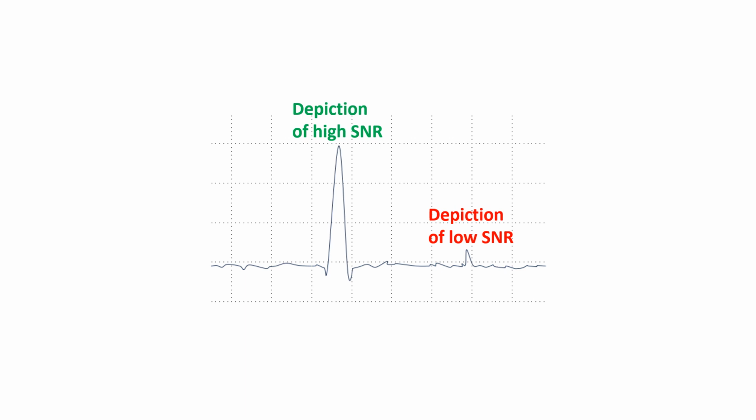A good communications receiver should have an SNR of 5 to 10 dB in bands below 30 MHz. A high SNR means that the signal is clear and easy to detect or interpret, while low SNR means the signal is obscured by noise and difficult to interpret.